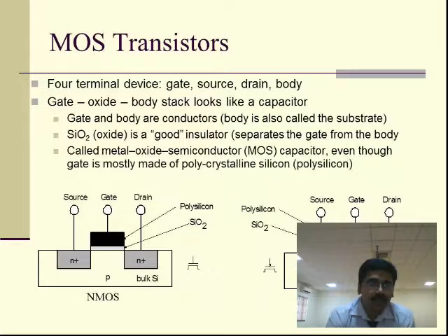That means the active portion of the channel will be concentrated on the source side instead of the drain side. The drain end of the channel gets pinched, and due to that the saturation region comes, and this particular region is called the pinch off region. The NMOS transistor goes to the pinch off region, and we cannot bring it back to the active region or cutoff region.